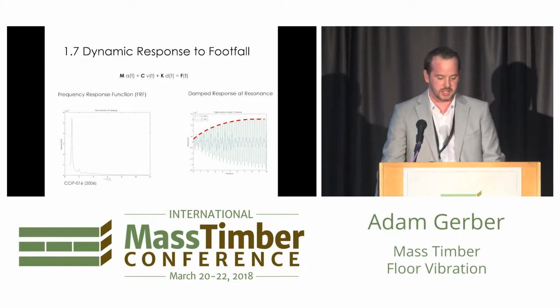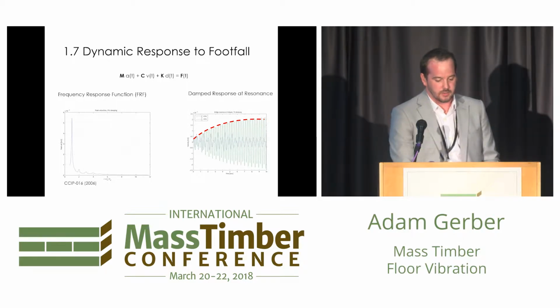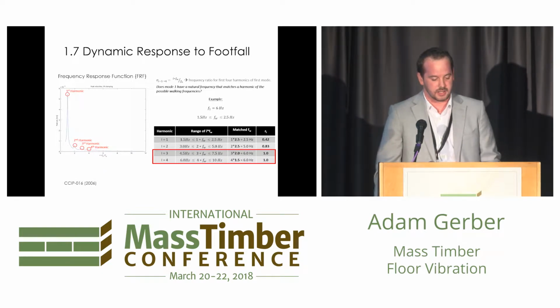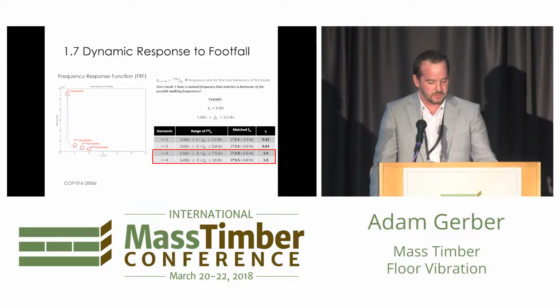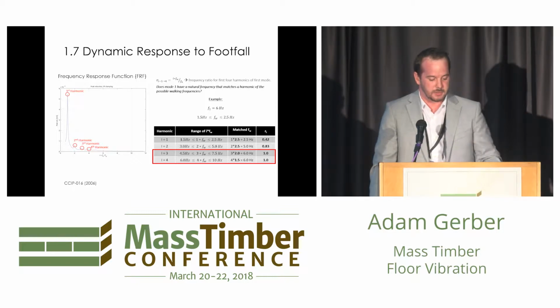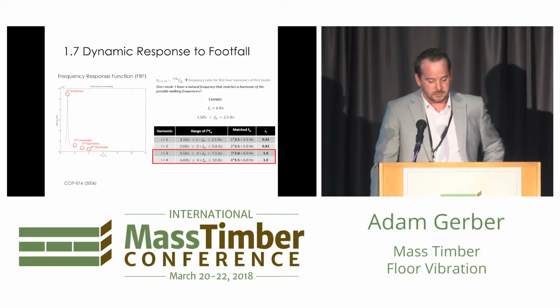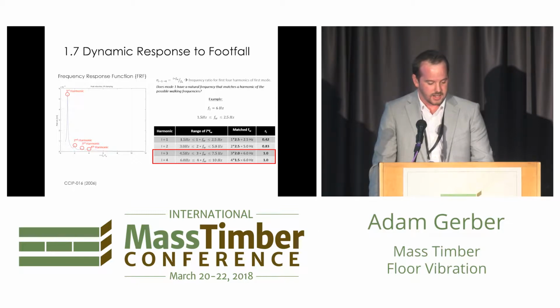So a frequency response function is basically if we did this analysis at every potential walking frequency, we could identify which walking frequencies cause the greatest response in our structure. And basically what it is, if you're exciting the structure at its first mode, you're getting a very high resonant response at the first harmonic. Typically what we see is that structures are excited in their third or fourth mode, due to the third or fourth harmonic of a walking frequency. And so we're really dealing with the third and fourth, which is quite a lower amplitude of vibration.